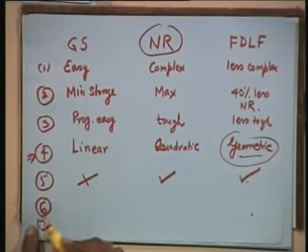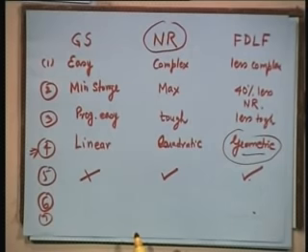Seventh, type of system. If it is a normal system, then Gauss-Seidel is no problem, but if it is an ill conditioned system, then Gauss-Seidel may have a convergence problem. Let me also tell you, some experts feel before doing Newton-Raphson, it is always advisable to have 1 or 2 iterations of Gauss-Seidel, but not necessary. This is just one opinion.